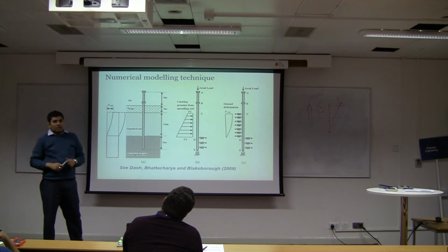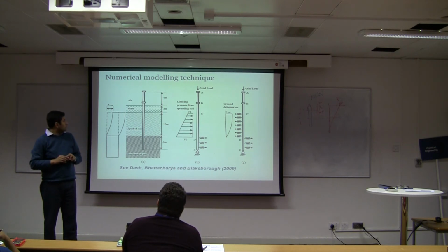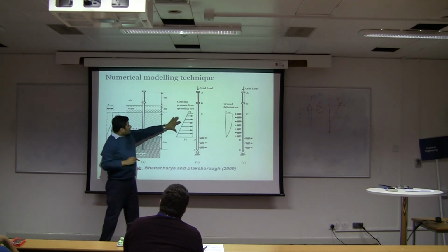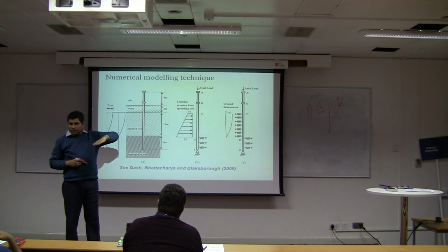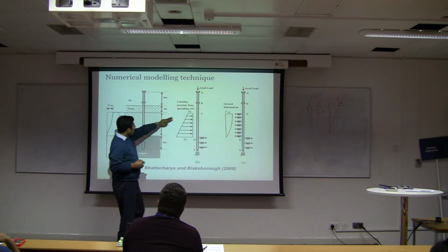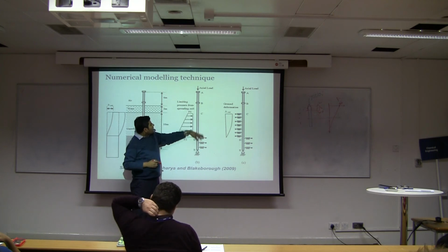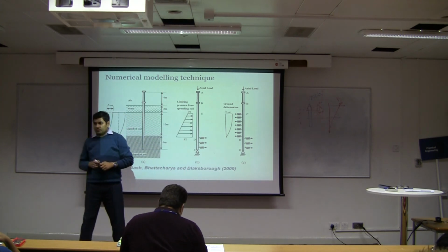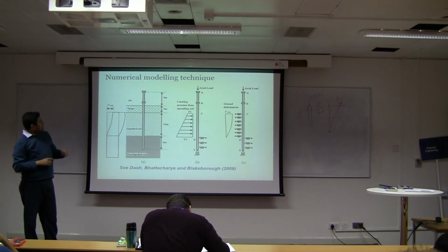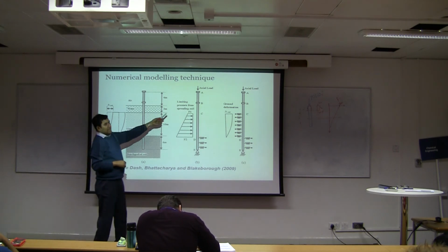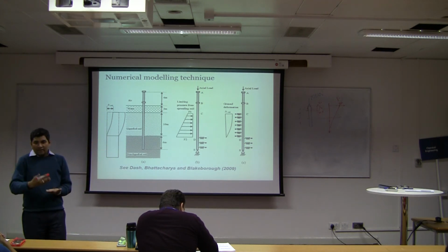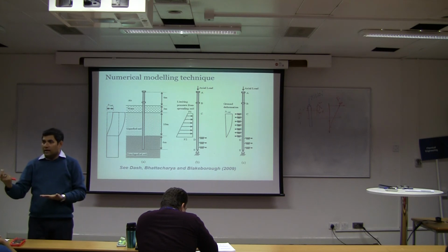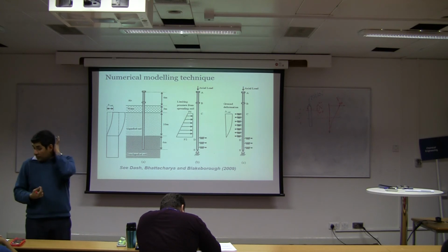Then scenario 1, the liquefied soil can flow. So you apply the force. You remember the Japanese code that you apply 30% of the pressure. So that will give you a force here, a force there. You can analyze this by hand, right? This is the limiting pressure method. So you can apply your pressure. Because at the end of the day, you have to find the bending moment and find out the reinforcement of the pile section. So you have to compute the bending moment.